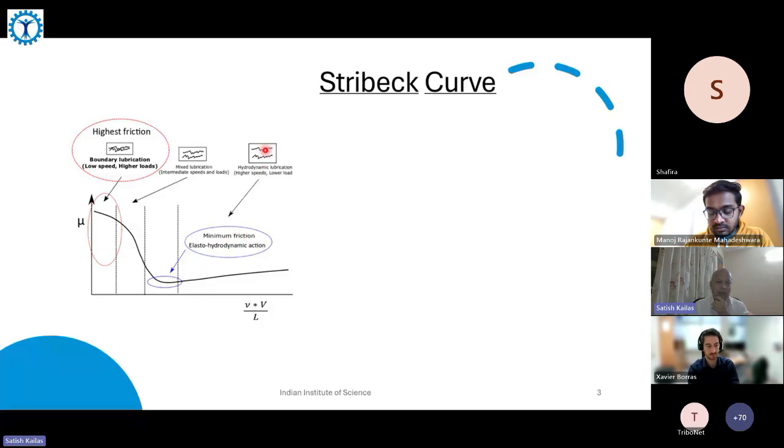So when you have the surfaces separated, the friction will be pretty low and only dictated by the viscosity of the oil and the viscosity index of the oil, because temperatures can increase during operation.